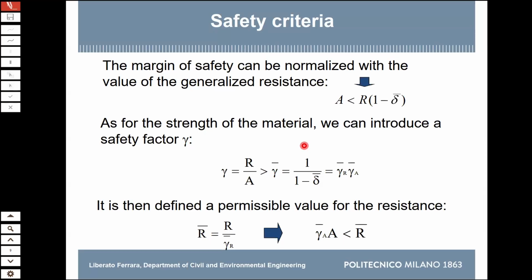Or once there was a grocery store, they had to store water. Well, you have the pallets with the packages of mineral water. Every cubic meter of water is 1 ton. If you have to store 3, 4, it's a huge live load. So this, just to show you that there is a huge variety of these numbers, and they come from different considerations and so on. So we have uncertainties.